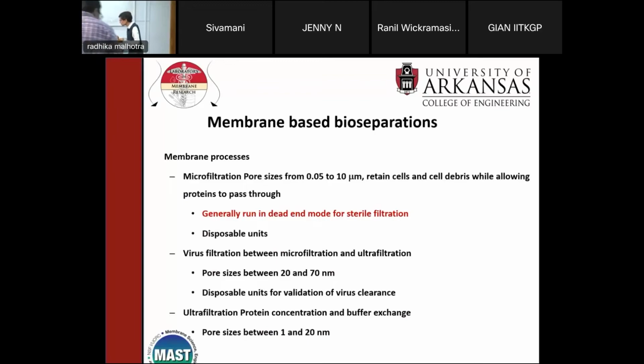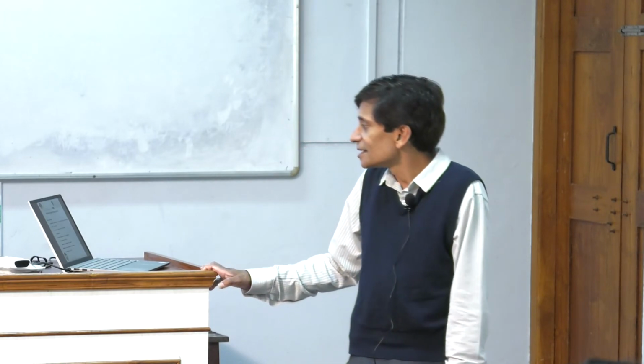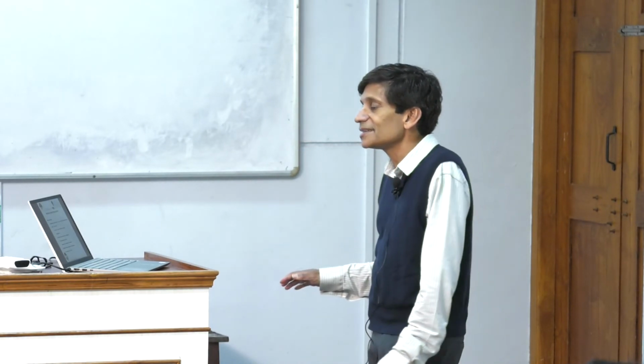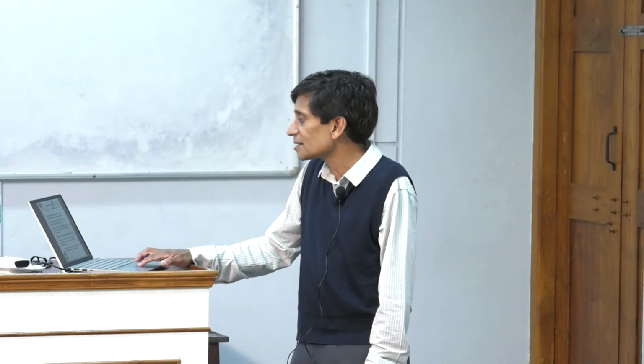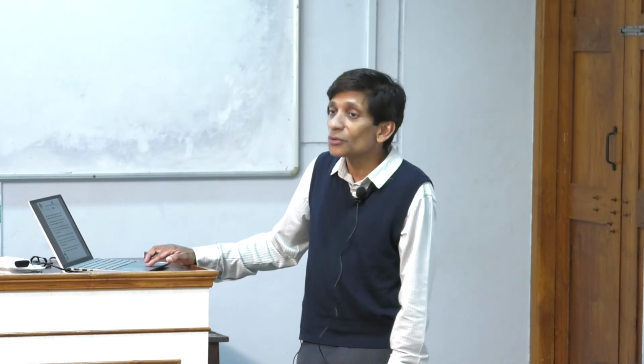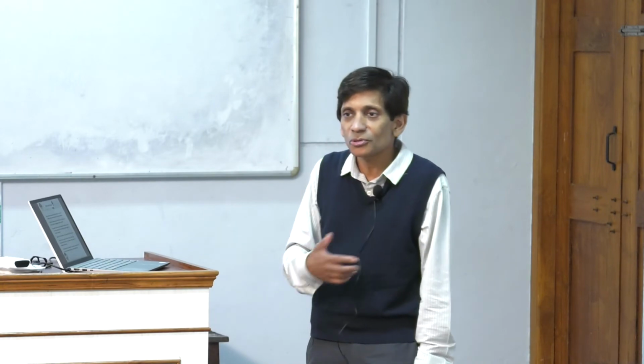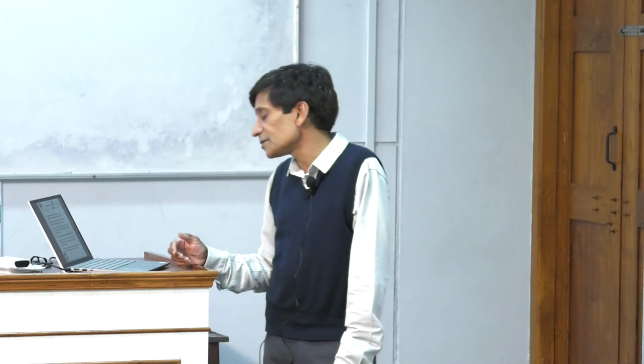So maybe this is a good way to introduce this. So we've talked about microfiltration, right? But sterile filtration is also a microfiltration process, right? Because I told you using 0.2 and 0.45 micron membranes. Sterile filtration is always run in dead end mode. Okay, always. You never run it any other way. And it occurs everywhere, okay? Most biotherapeutics are processed by sterile filtration since thermal stability of these molecules prohibits use of alternative methods, right? Other ways to get rid of microorganisms, you can do gamma irradiation, you can do autoclaving, you can do all these things. Your protein is going to be destroyed, okay? So that's why sterile filtration is important.